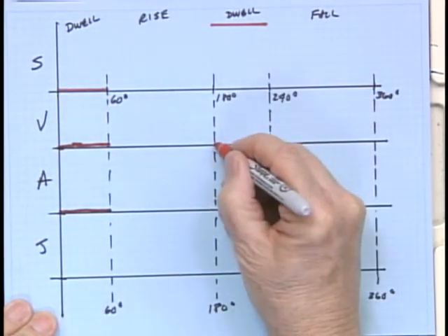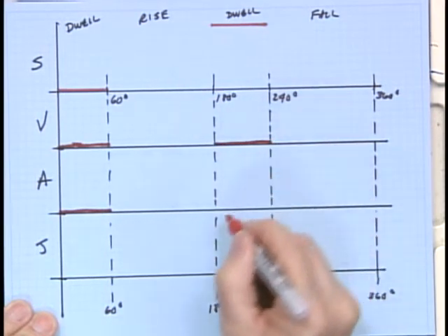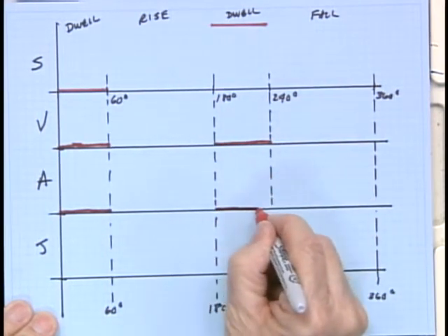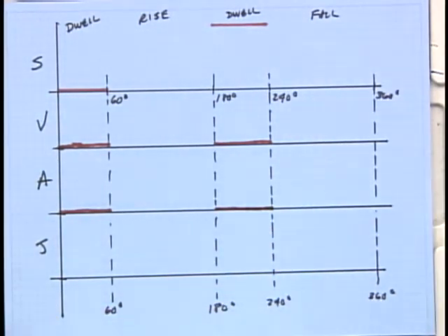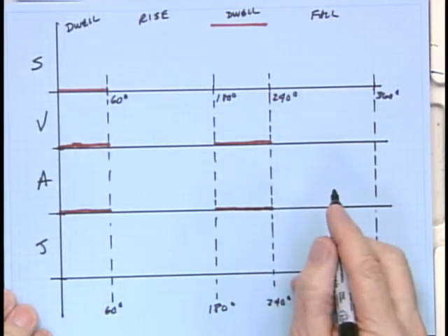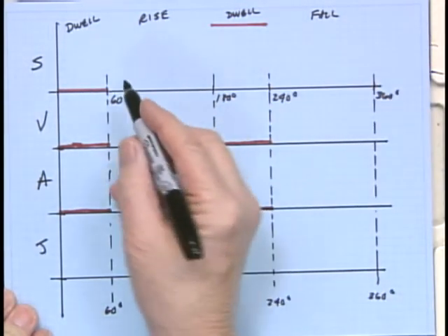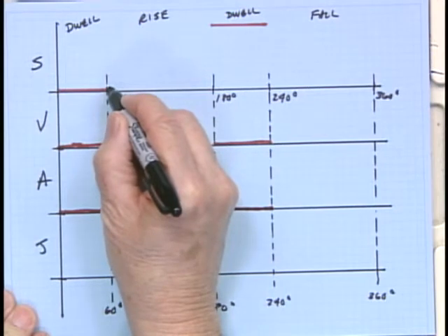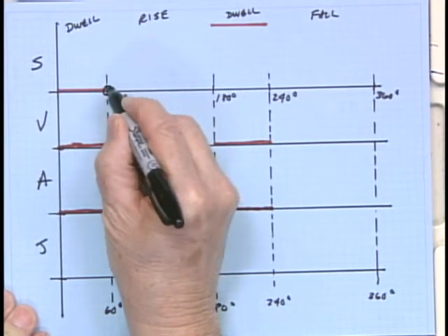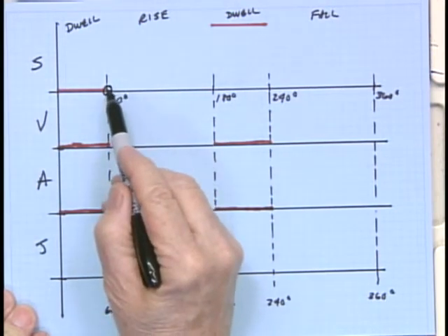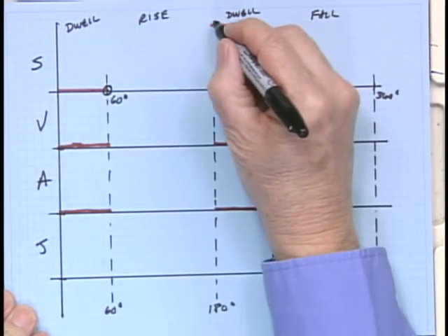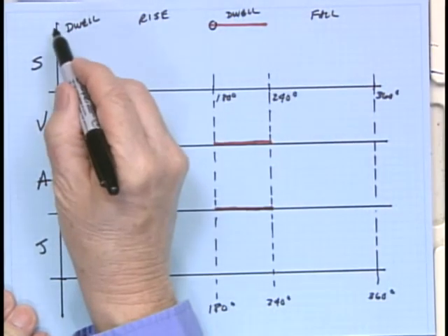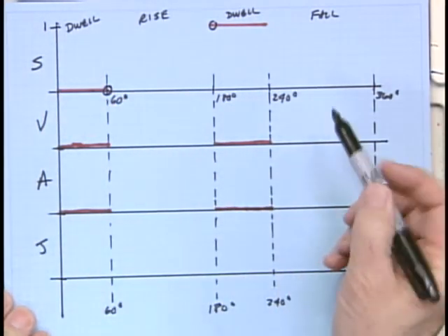So during those events, which bracket the rise, I have 0 values. Well, in order to maintain continuity, i.e. obey the fundamental law, I have to have a value of my displacement rise of 0 at that point to match this, and I have to have a rise of, we called it 1 for this example here.